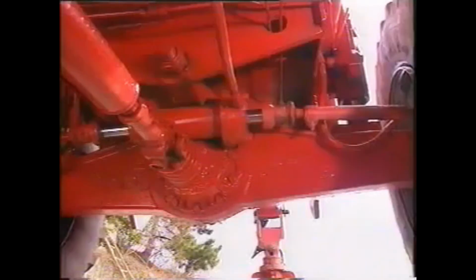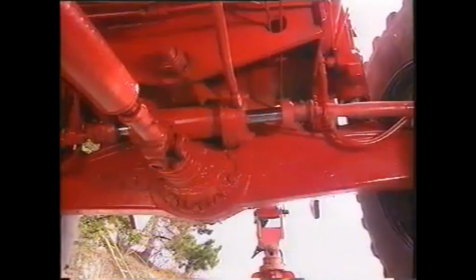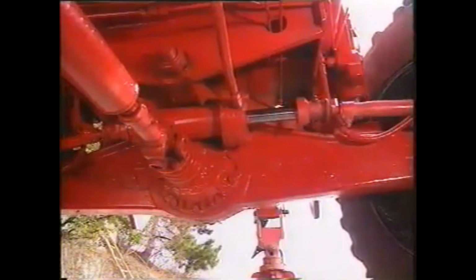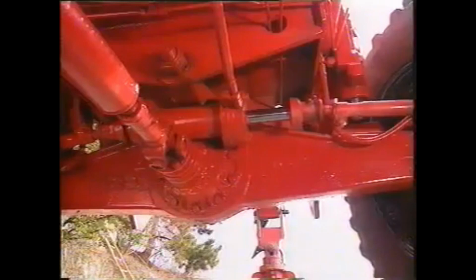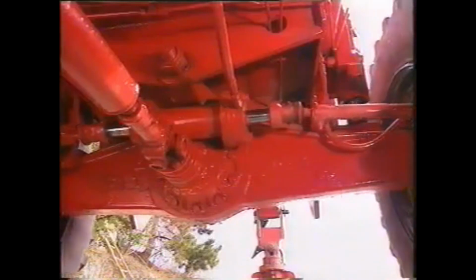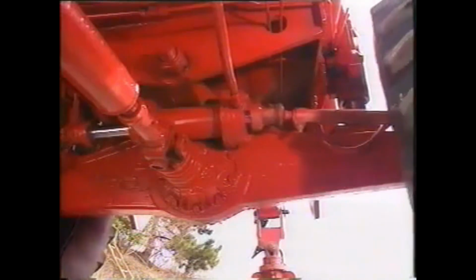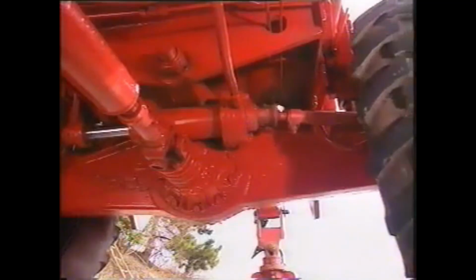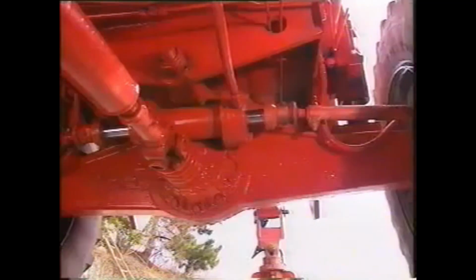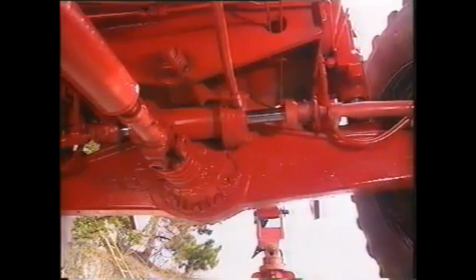Varying piston speeds would be undesirable in this hydraulic steering mechanism because steering movements to the right and left must be at the same speed. For this reason, a balance cylinder was used in this case. A balance cylinder is one with a double-ended piston rod. An additional advantage of a rod like this is that it can move elements on both sides.